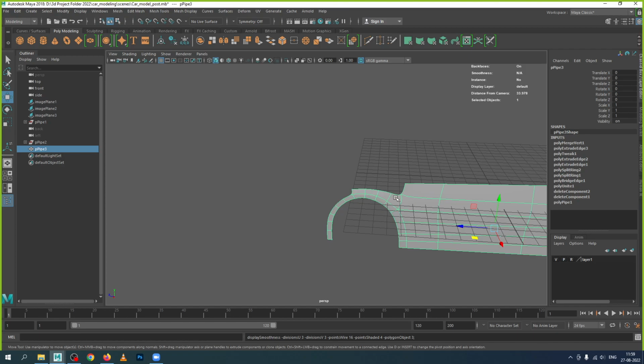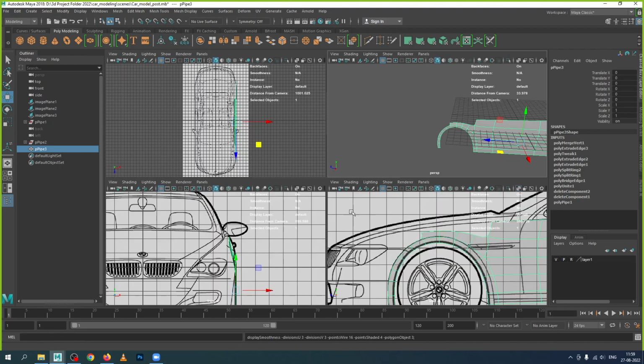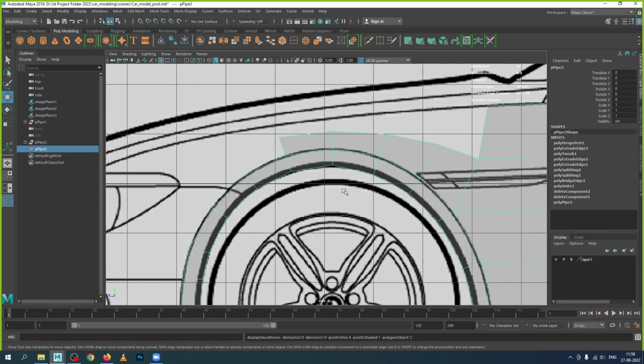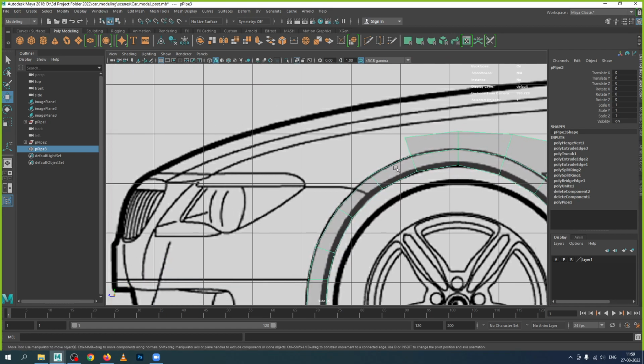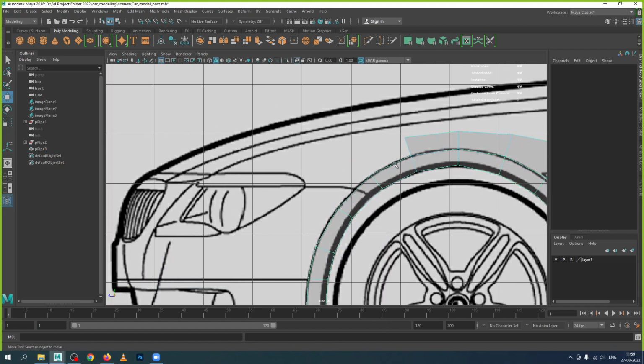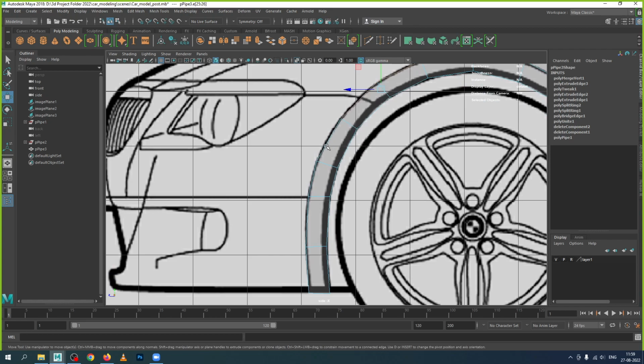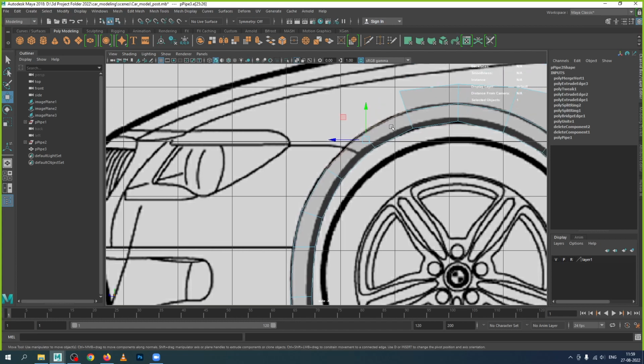Now let's come back again to the front view, press 1 key. For making it a little flat, select this edge now. Edge selection 1, 2, and right now these 2 we need to move up, and this one will go into the front area. Otherwise if you want you can select this one also. Why am I doing it separately? Because it will go in one direction first, then it will add a separate extra surface over there. So I am not adding this one now because it will go into the front area. I have selected only these two.